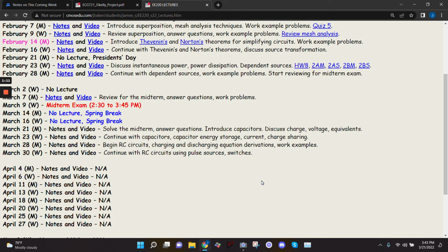Because the capacitor's two plates aren't actually touching, and they're just building charges opposite of each other, there is no current flowing through a capacitor, correct? That's right. So capacitors have what's called displacement current. Basically, if you push, no current will flow. That's something I didn't mention today, and I should say real quick. In a DC circuit, a capacitor acts as an open. It basically acts as an open. So if I put 5 volts here and I put 0 volts there, nothing's going to flow through it.